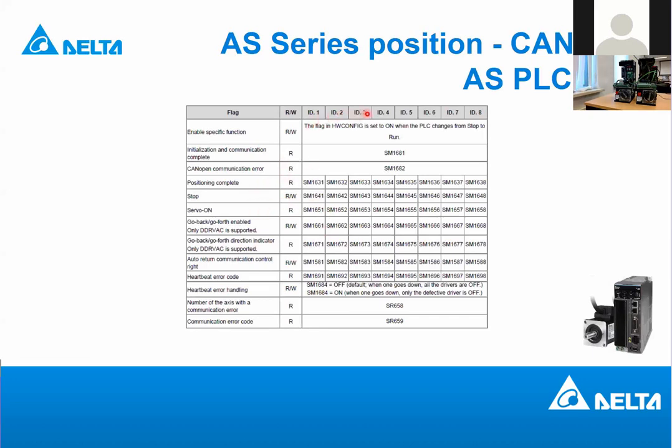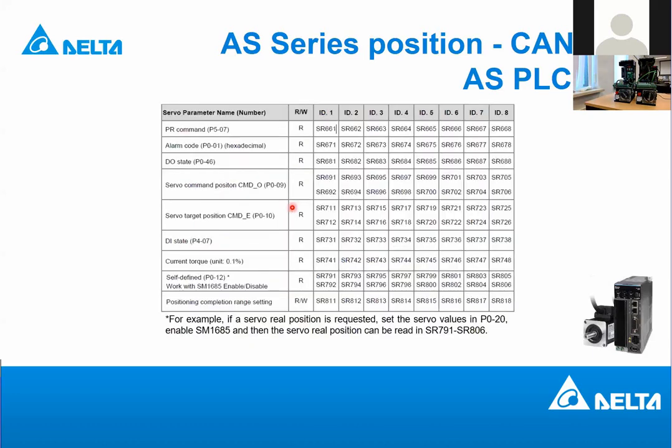For example, for slave 1, slave 2, slave 3, slave 4, is the servo on? Is this drive enabled? Then you can read the status of this flag. And besides this, there are other parameters indicating what you would like to know about the network, about your drive. Depending on the need of your machine, you can use one of these special registers. It's like a feedback to know what is happening in the machine. So there is quite a lot.